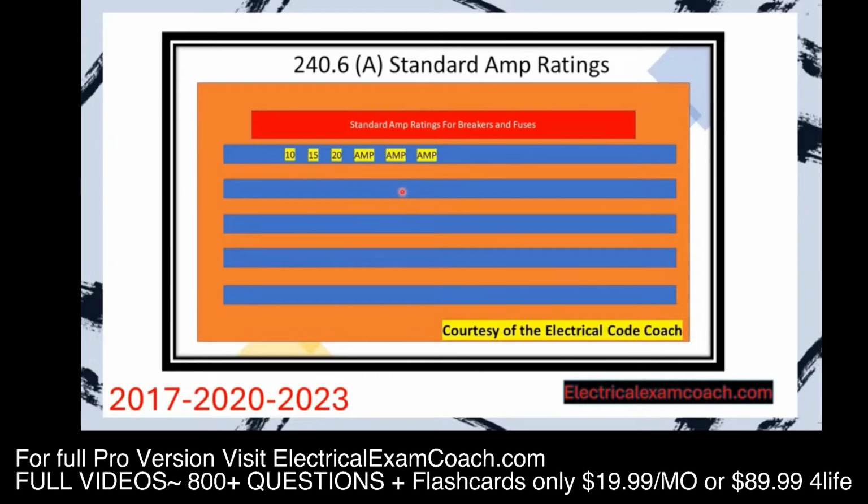The manufacturers make these size breakers. The stores stock these size breakers. Installers purchase these size breakers, and when we are doing our load calculations in the NEC, these are the sizes that we're actually going to use. We're going to learn all about it in this lesson. Table 240.6(A), standard ampere ratings for breakers and fuses.